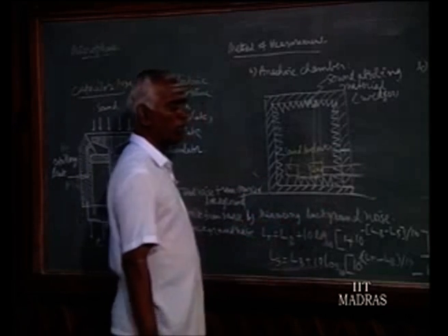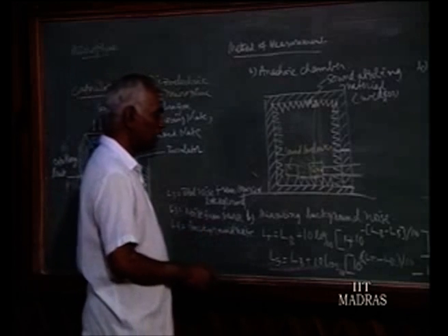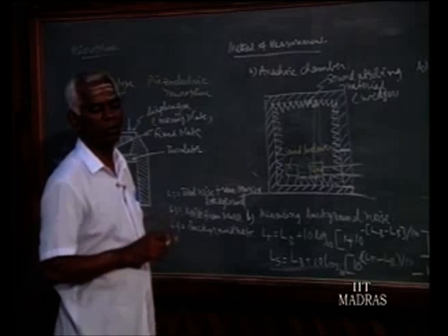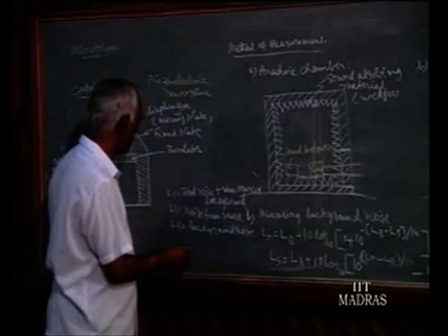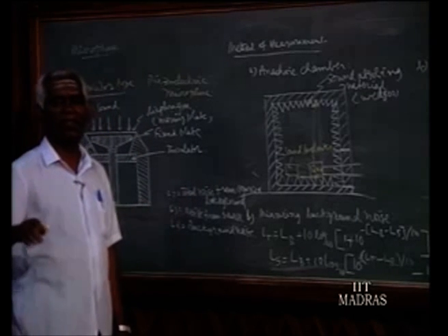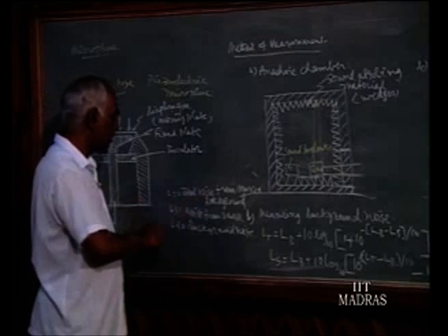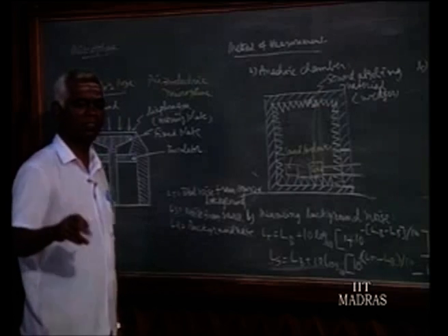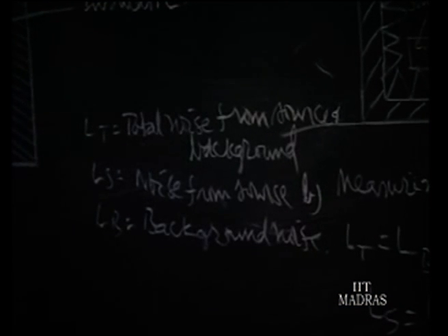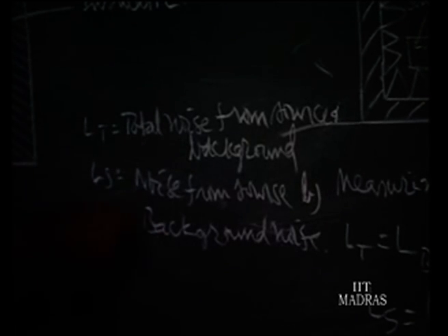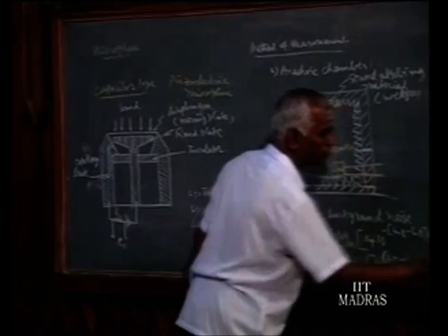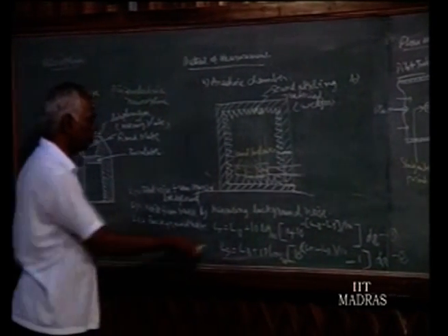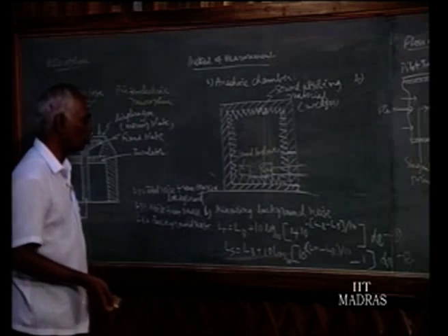The second method is by measuring the background noise also; we can measure the noise made by the device. Now you have to make two measurements with the sound level meter. Suppose the source is there making noise and the surrounding also will make noise. So you make one measurement called total noise, where the source is running and atmospheric noise is also there. Now you switch off the source, it is a running machine, so you switch off the power supply, the source will stop, no noise, so you will be measuring the background noise. So you measure the total noise and then after switching off measure the background noise. From these two measurements you can obtain the source measurement by using this equation 1. Equation 2 is obtained from 1 only, but it is in terms of our required quantity. We want to measure the source noise, so you can use it.